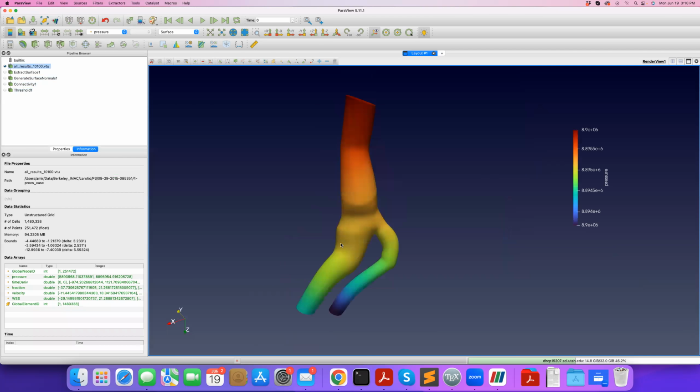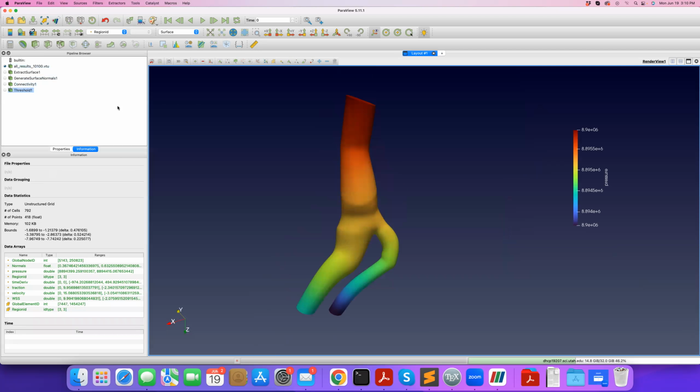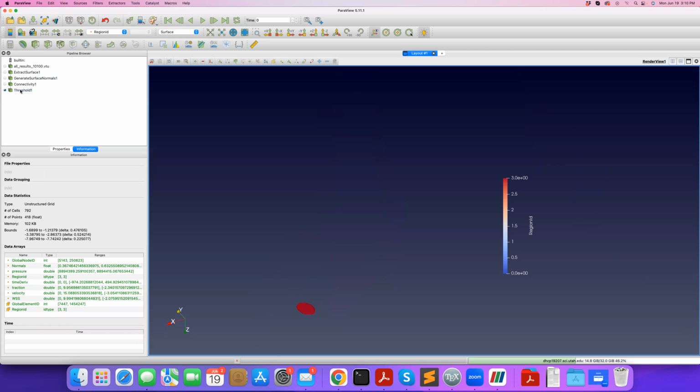So you'll generate IDs for everything, and then you use connectivity to take out different boundaries. The IDs will be attached to it when you threshold out different boundaries and save them in different files. So you know within your global mesh where each node in this local face sits. You can create something similar to what CMascular creates if your mesh comes from something else, but you'd like to use the same functionality that we talked about in some of our previous tutorials.